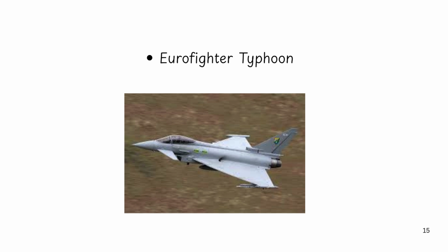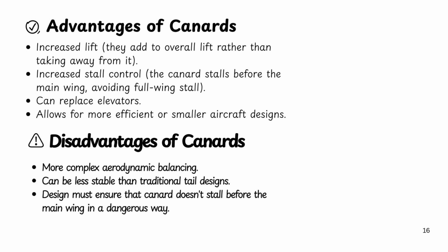Canards can also improve maneuverability, especially in fighter jets, because they give extra pitch control at high speeds or during tight turns. In short, canards generate lift, enhance pitch control, and can improve both safety and agility, depending on how they're designed. Now, let's look at canards.